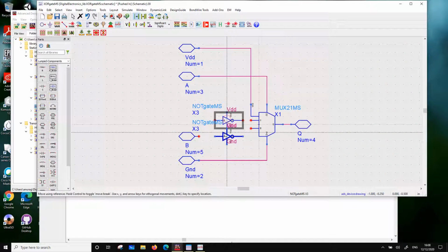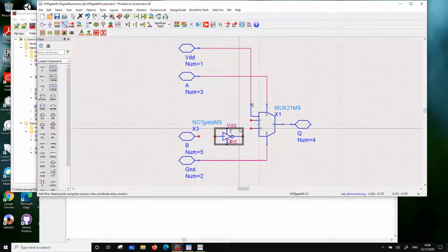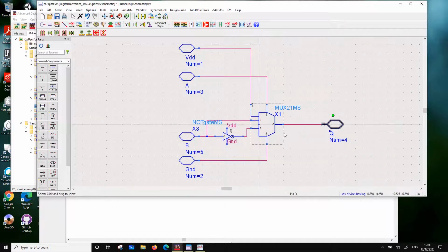Now the same thing is going to become a XOR gate, and then I'll put one inverter to get rid of those glitches. So I can take this inverter and put it over here, one inverter over there. Copy of this, I'll put it over here. So now the same thing is going to be an inversion following the gate, and this inverter will take care of those glitches, though this will increase the delay, right?